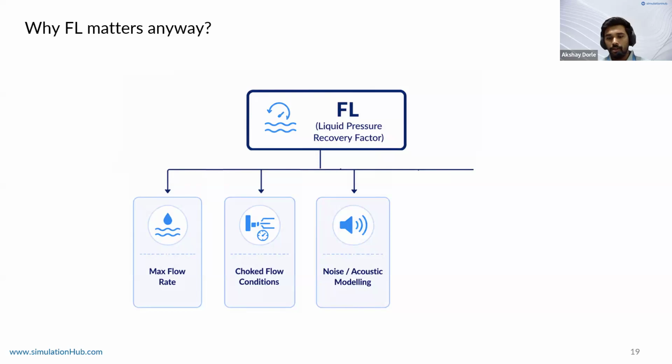We also need FL to accurately model noise. As we have seen in previous webinars, noise, even in various standards, VDMA or IEC standards, requires a good prediction of FL. It depends on FL apart from the other parameters as well, but FL is one of the key contributors to this evaluation. So for complex geometries, noise attenuation devices, anti-cavitation trims, it becomes very essential that you have a good value of FL.